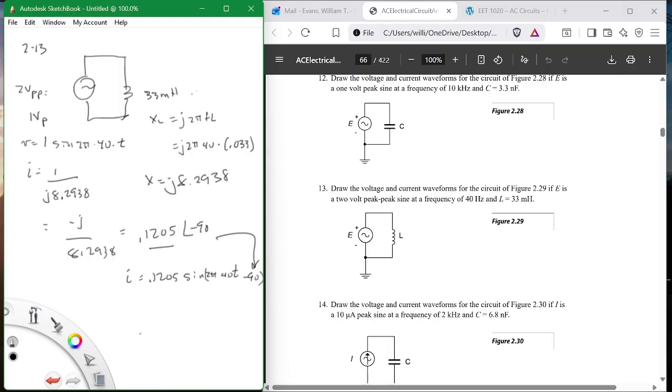Now with this case, the voltage is the sine wave, and the current is like this. It's lagging by 90 degrees. So this is my voltage, this is my current, and my current is lagging by 90 degrees. If you had a pure inductor, you would see this 90-degree shift. ELI: voltage is ahead of current in an inductor, all right? You see this shift.